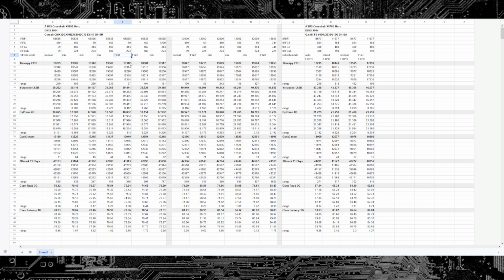Even FGR is just not that bad once you set refresh interval to 65,000, unless you do something dumb like setting all of your tRFCs to the same thing, which is a thing I regularly see from Intel users, which is stupid because Intel defaults to FGR and has always defaulted to FGR. And I've also seen people do that with the new AMD AGESAs, and you're not losing a ton of performance, but it's still stupid.